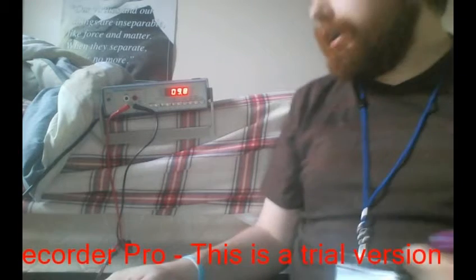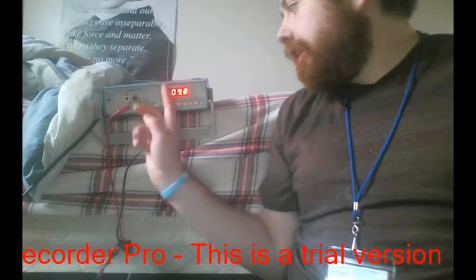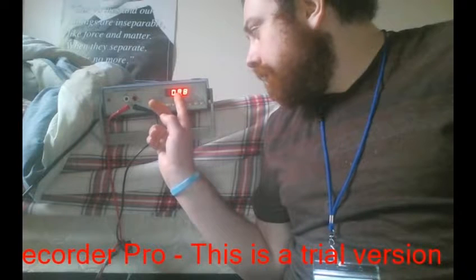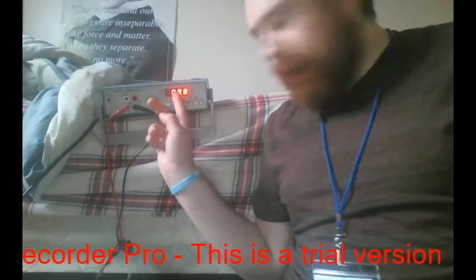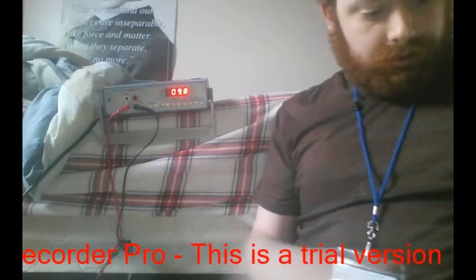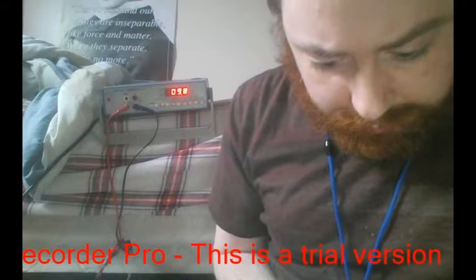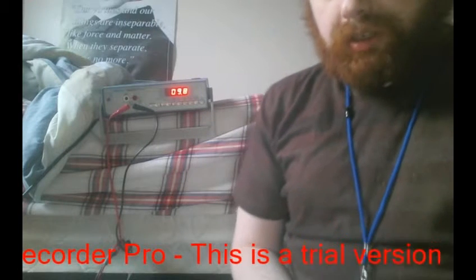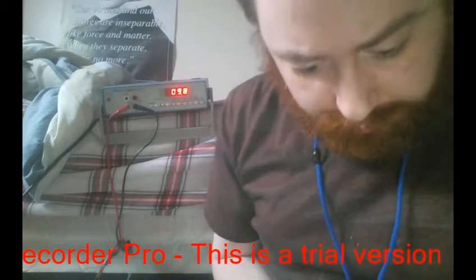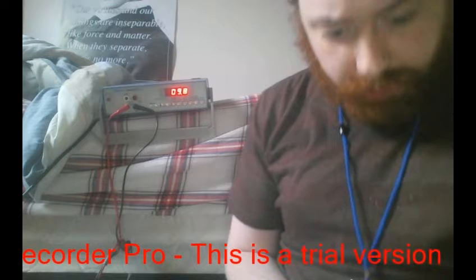Okay, I hooked up a 1 nanofarad capacitor to it, measuring it. Right now we're getting 9.8 microamps, I believe. Yeah, microamps. I entered it into the calculator. We get close enough to 1 nanofarad, just off by a few picofarads or so.